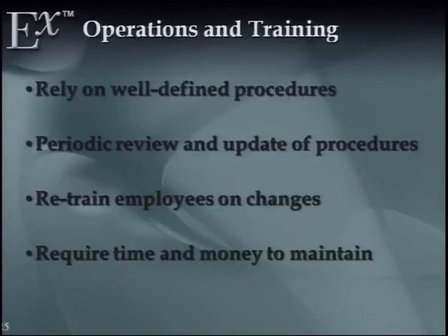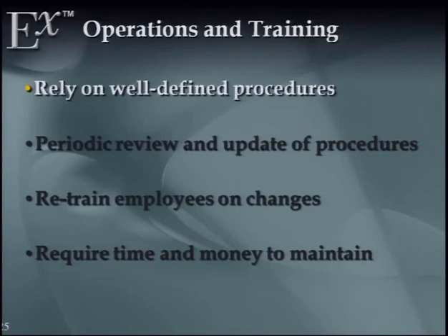Operations and training. One of the benefits that we've found from creating checklists like this, going out into the boiler house and using them, is that it helps facilitate training for staff and understanding the hazards. As with any PHA, it requires good, understandable, well-defined procedures.